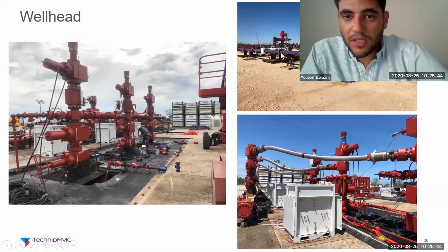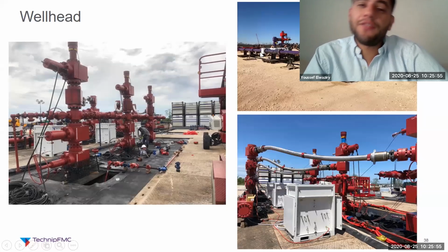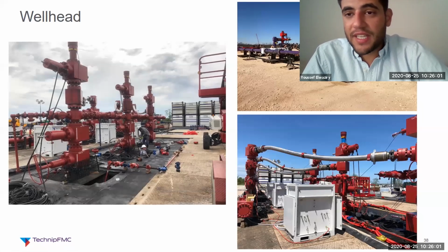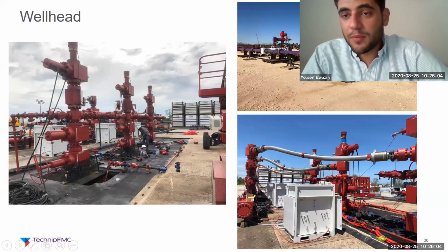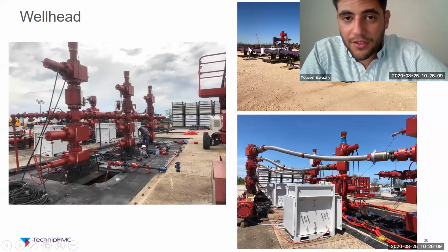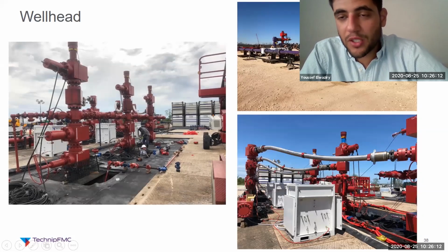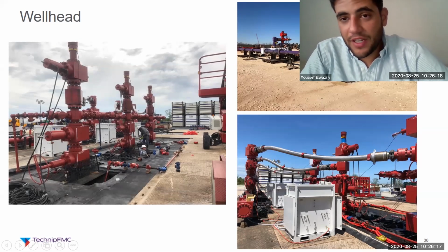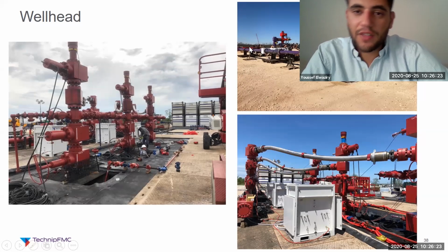This is another layout where you also see your 3 wells, red, white, and blue. And then these would be zipper manifolds. Zipper manifolds are used to control the flow. So let's say if we want to pump in this blue well, we would close the white zipper valves that are here and the red zipper valves that are here, and the flow is only going to be going to the blue well, and vice versa. If we want to only frac the white well, we would close these zipper valves here and the zipper valves here.